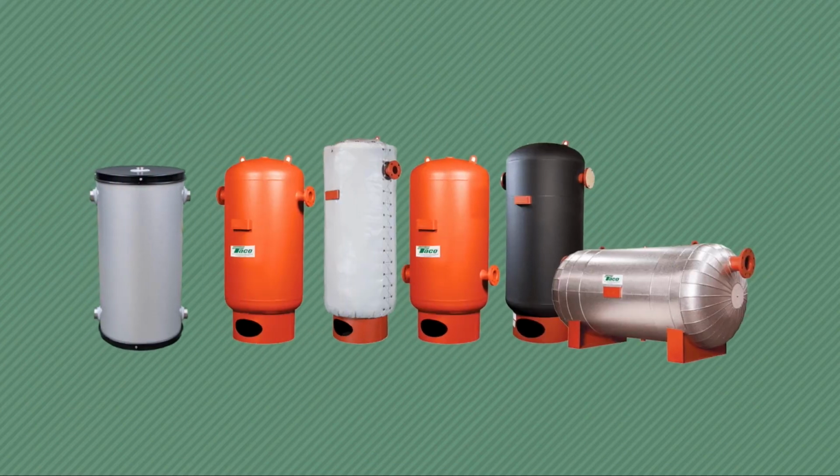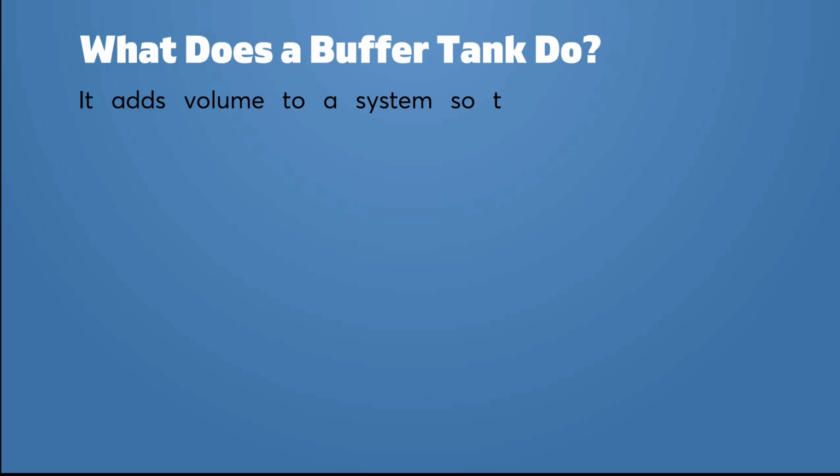There are various materials used for buffer tank. However, SS316 or SS316L is the most common material for buffer tank. However, it depends on the project, and the selection will also be based on that. What does a buffer tank do? It adds volume to a system so the heat pump or chiller operates efficiently.